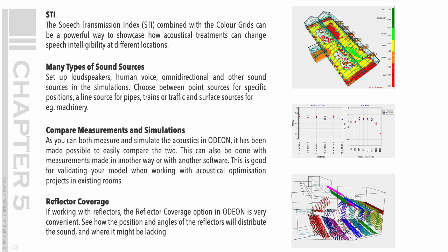Many types of sound sources. Set up loudspeakers, human voice, omnidirectional and other sound sources in the simulations. Choose between point sources for specific positions, a line source for pipes, trains or traffic, and surface sources for example, machinery. Compare measurements and simulations.